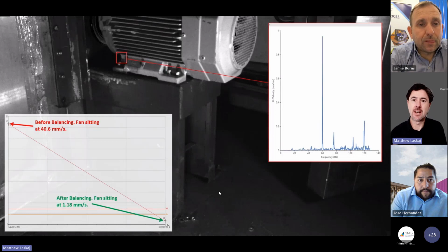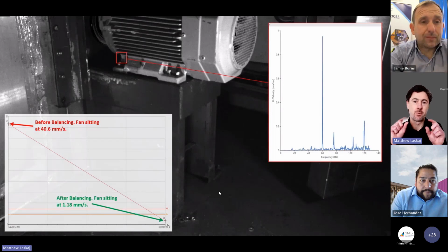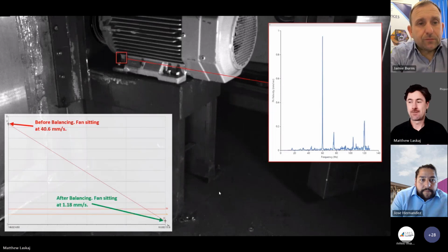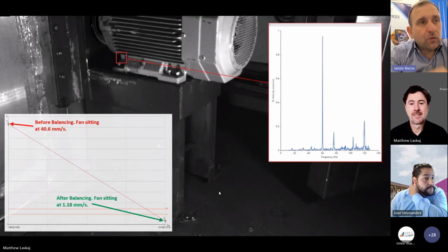I worked in the refinery, and every 16 weeks we'd overhaul this one part of the process. But even though we'd replace the coupling and we'd replace the gearboxes, after about 8 weeks, they'd fail again. They're like, oh, it's because the vibration levels of the drum are too high. Well, in fact, it's because people weren't able to tighten up the bolts properly on footings, and they were shaking themselves loose too quickly. Same thing, different cause, but we see a lot of that.